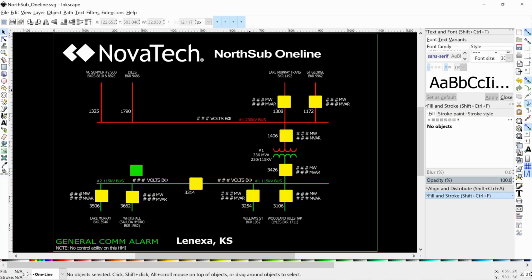What I'm going to do is add in a couple breakers and some analog data to show you exactly how the full configuration of the HMI screen is created. So now you see here, we've built up these objects, these breakers, these analog data, and then we have some static descriptions like the volts, megawatts, megavars, and the line names and so on.